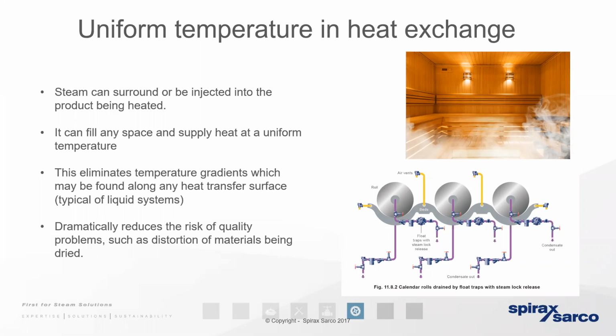We get striations, we get cold spots. And it's a little bit like understanding the inefficiencies caused by failing to bleed your radiators at home. Well, we simply don't have that issue using steam because it's a gas. It's not a liquid that falls due to its density to the lowest possible area of the heat exchanger. And we also know that because steam gives up its heat energy by condensing, the heat exchanger will only draw the energy in the steam towards the process as and when required.